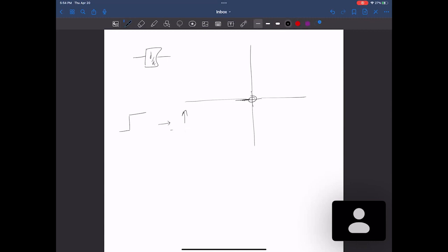It's not necessarily going to be a problem if you plug it into a full, complete block diagram, because other parts of the block diagram will interact with it. But in general, we don't want to have a differentiator by itself in our design. We always want to filter it so that it does not react to noise. A differentiator by itself is going to react to noise.